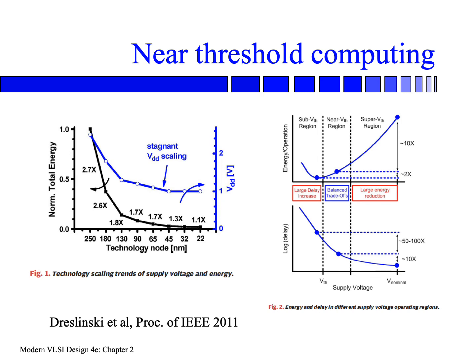The reason is that the chip becomes more leaky, because accordingly you have a reduced threshold voltage. Sometimes the leakage current can be even more significant than the active current. That's one of the drawbacks if you go beyond the threshold voltage.